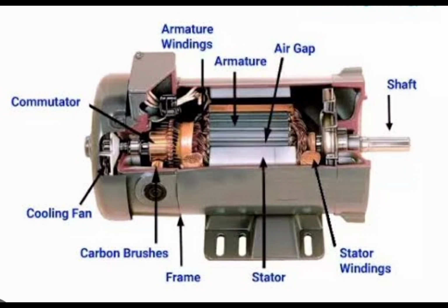It is also one of the most essential parts of the DC motor. Field windings. These windings are made with fixed coils, which are copper wires. These windings are wound around the slots carried through the pole shoes. Next, armature windings. The construction of these windings in the DC motor is of two types, lap and wave.